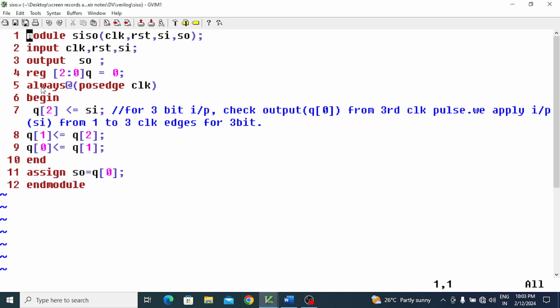Okay, so this always block is called a procedural block. Always procedural block. So in this procedural block I wrote different statements, multi statements. So when there are multi statements, I should use begin end, so that they will execute one by one. And this is a behavioral style code, so I should use this non-blocking symbol, non-blocking statement symbol. You can see this symbol is called non-blocking for these statements in the procedural block.